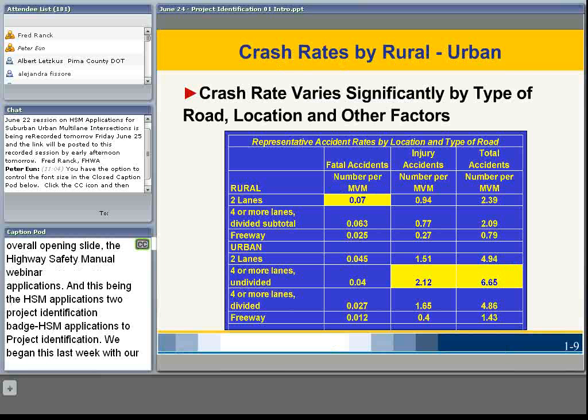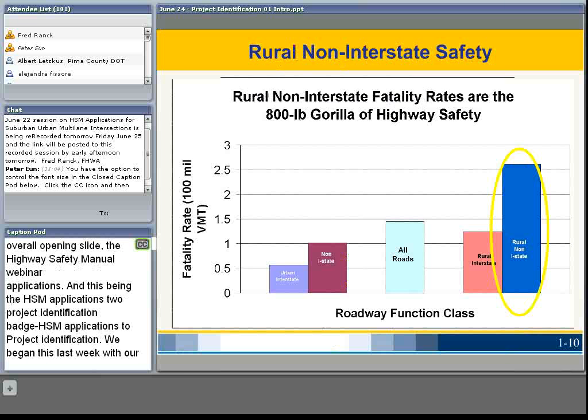Many of us in the highway profession, the highway engineering profession, transportation engineering, have known for a long time that adding two lanes to a two-lane highway to make four doesn't necessarily make for the best operational design or safety performance design. And the rates for injury crashes and total crashes clearly show this to be the case for undivided multi-lane highways.